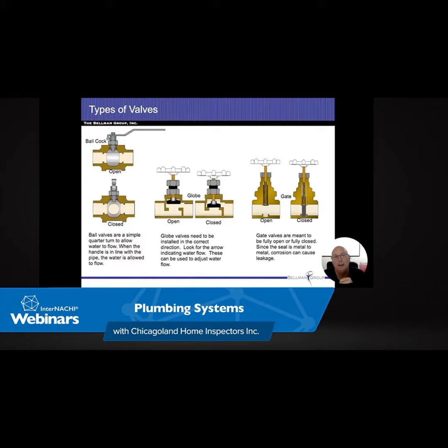All right. So this one here is what we're showing is over 80 psi. As we come in, this water's coming in from the right, and it goes up to our shutoff valve. Then it goes into our pressure reducing device, and then we're going to have a pressure relief valve right after that. Sometimes the pressure reducing device and the pressure relief valve are actually built into the same thing. And then our water meter, and of course we're jumping over our water meter, pressure reducing device, and pressure relief valve, just in case those have to be reduced.